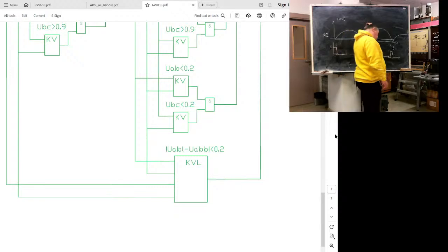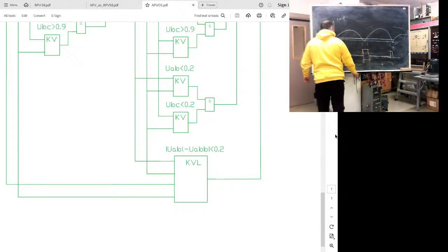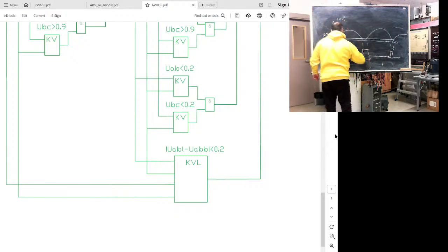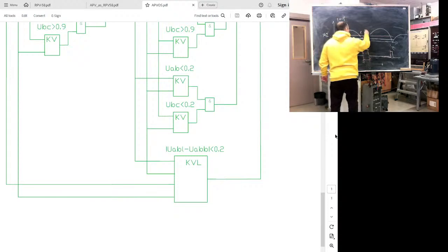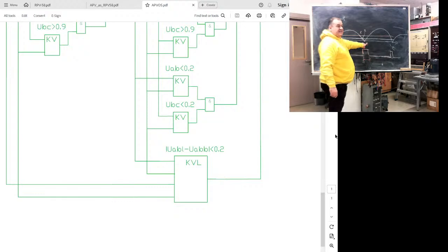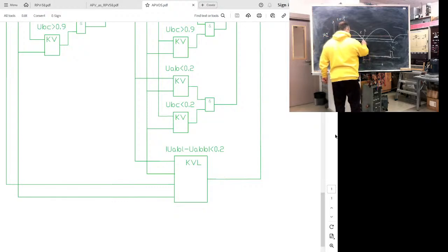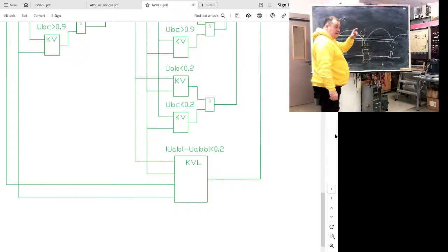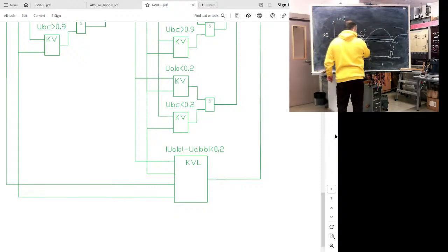zero disturbance. To do so, high-end recloser logics have two borders, trip 1 and this one, trip 2. They extrapolate when the 0 point is, they solve an equation and send the on command with a so-called ahead time. They need to solve an equation to send the switch on command in such a manner that the switch contacts, circuit breaker contacts, will close in this moment of time.